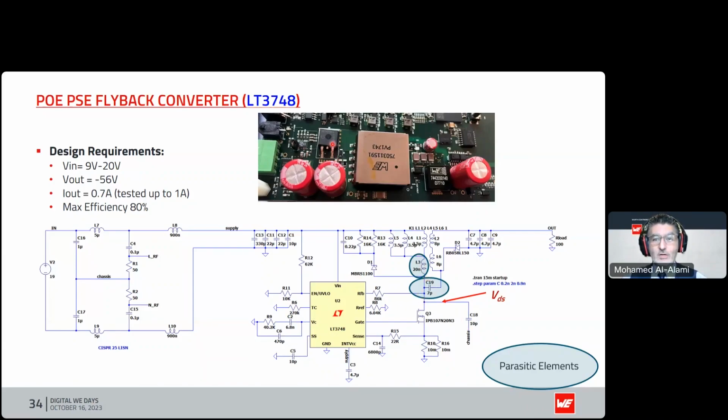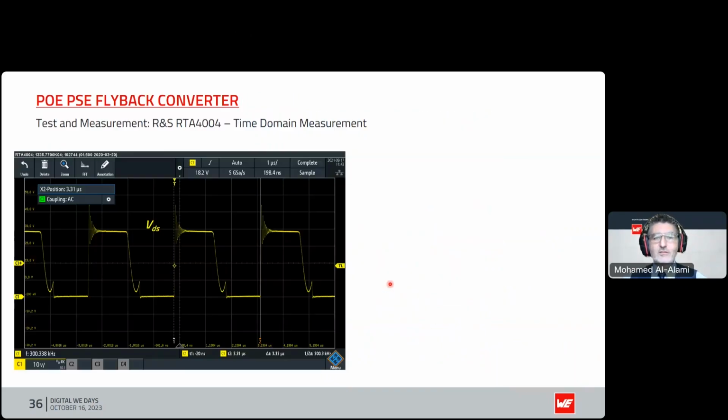As you can see, it's set right on top of a nice ground plane here to get rid of the heat. We've got our LISN at the front end and our cable simulation, or estimation of the inductance of the cable. And we see with all of these, there's a lot of correspondence between the tested data and the simulated data.